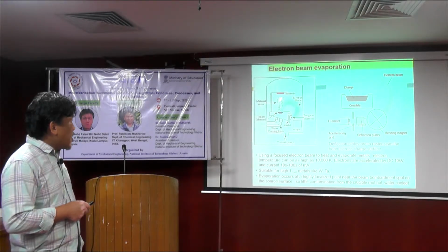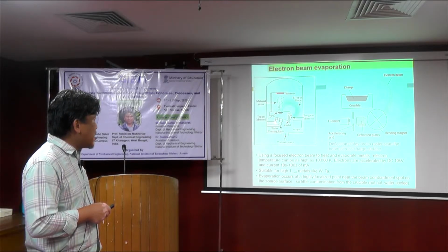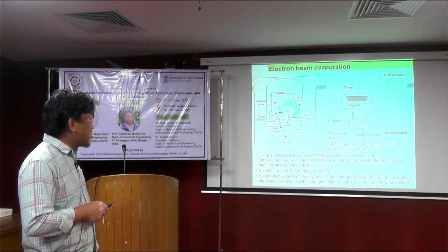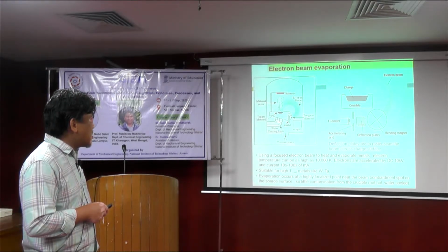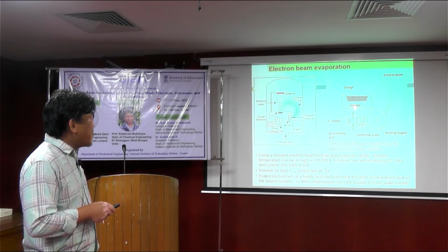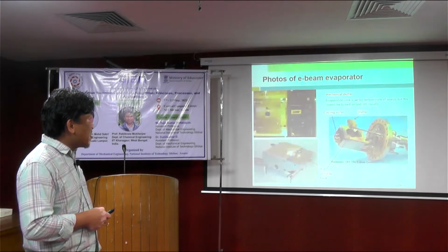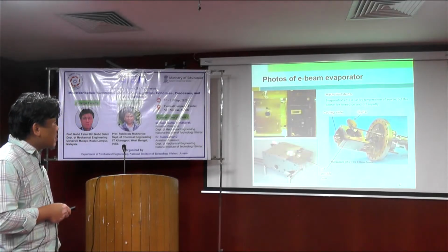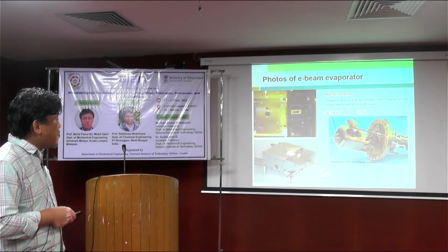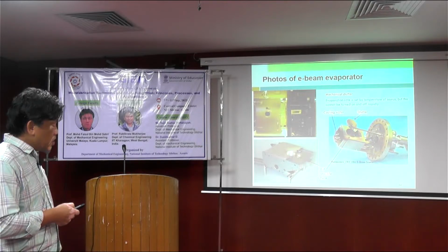And this is for electron beam evaporation. It's just a matter of different heating method, but the process mechanism is the same. So you have your crucible, you heat up using the filament of the E-beam here, electron beam. Then you can have your material evaporated. So this is the setup of the E-beam. You put your crucible here, basically.